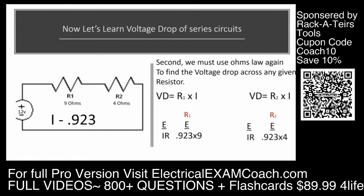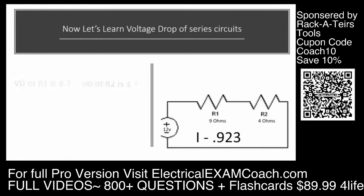On this other side here, we just plug in the knowns. We know the amperage and the resistance, and we just multiply that, and that's going to give us the voltage drop. So the voltage drop of R1 is 8.3 when we did our multiplication, and the voltage drop of R2 is 3.7.